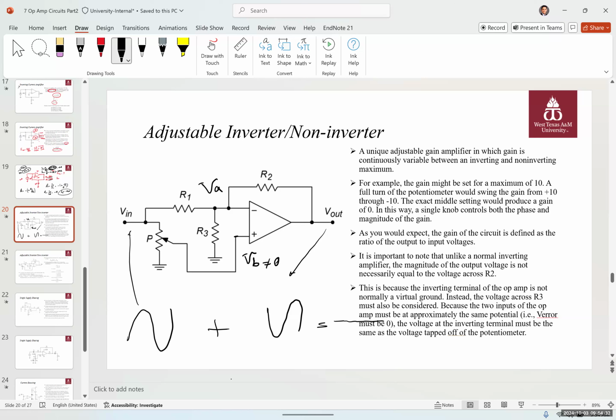Other applications are for phase shift, obviously. And when you have a gain of zero, it means the output is zero, so it can completely cancel a signal as well. Imagine you using this as an audio amplifier. When you change the potentiometer, the gain could potentially go to zero and completely eliminate the output and the volume on the output. There are a lot of applications for these. Communication systems is one application that we use a lot. In PWMs, we use this type as well.